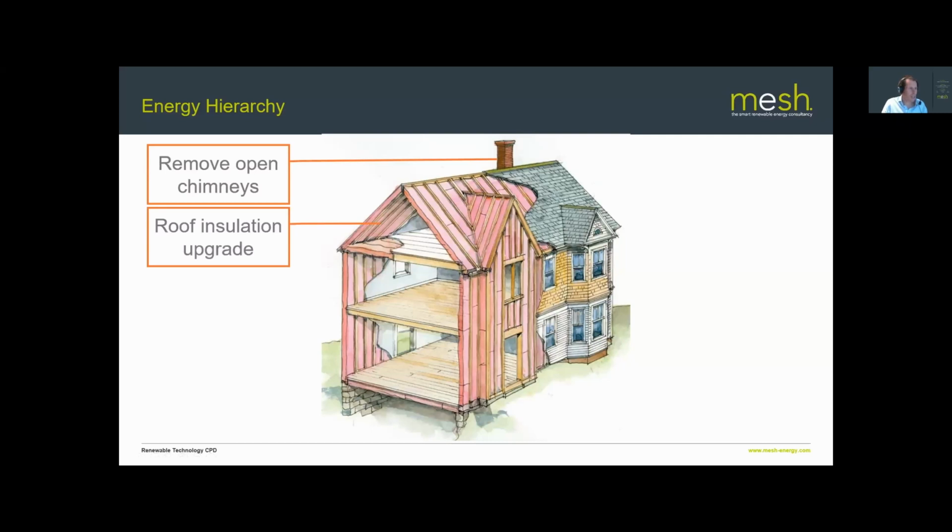Obviously, roof insulation, hot air rises, we know that. So depending on what you're using the roof space for, you might well go for a cold roof, or we might go for a warm roof. Obviously, a cold roof may well be more efficient because you've just got this flat surface, smaller surface area which you're trying to insulate, and you can build that insulation up quite thick quite easily. But roof insulation, absolutely key.